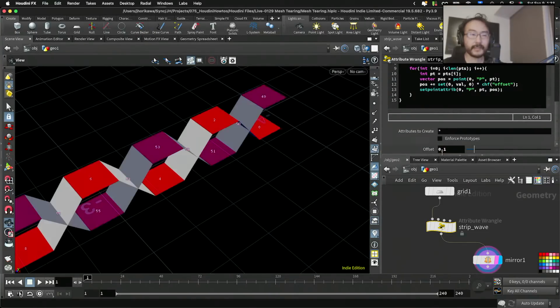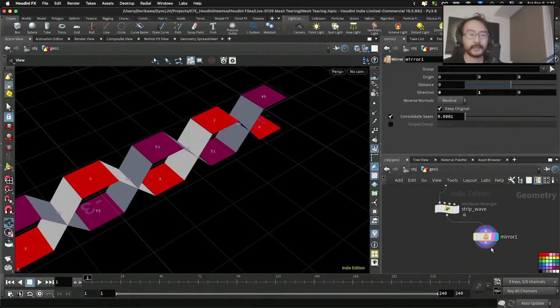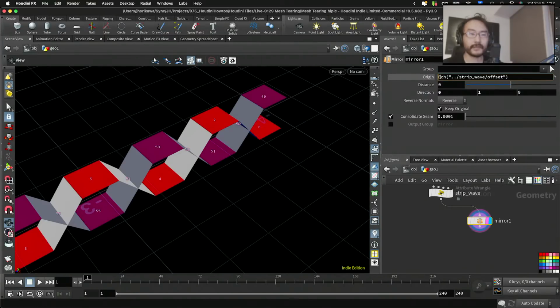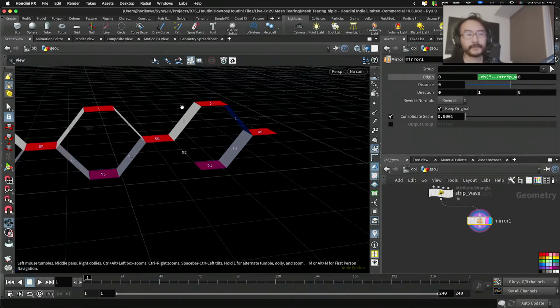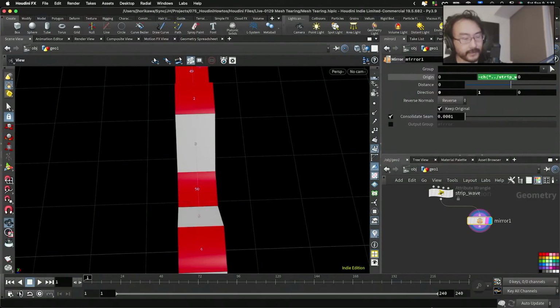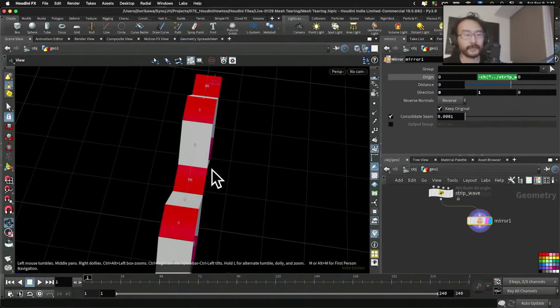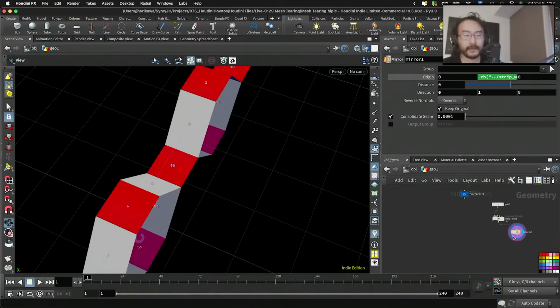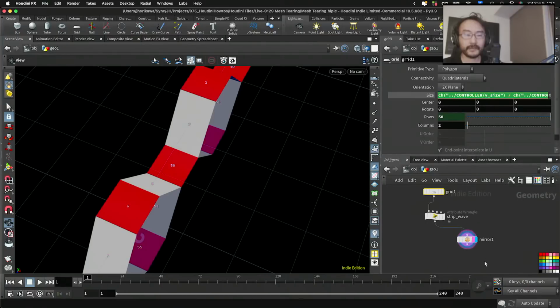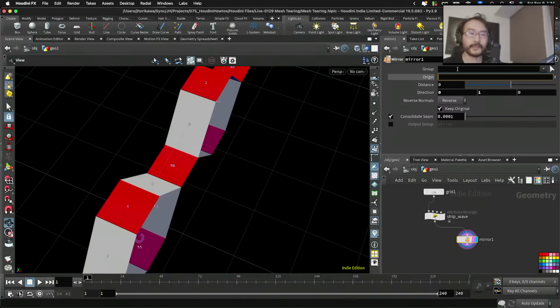Let's make this 0.1, copy this, and set origin to negative offset, so negative 0.1. Alright. Now I also want to shift this in an X direction, to the right or left, by the size of this width. So I could do that by, where is it, this is the X size. So I can copy this here and paste it to this origin X.